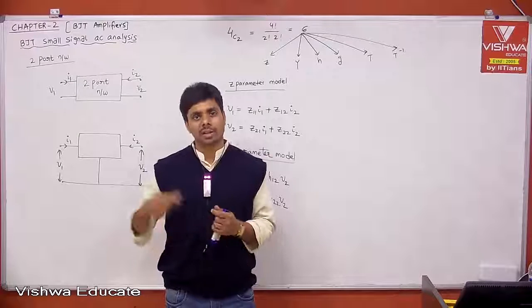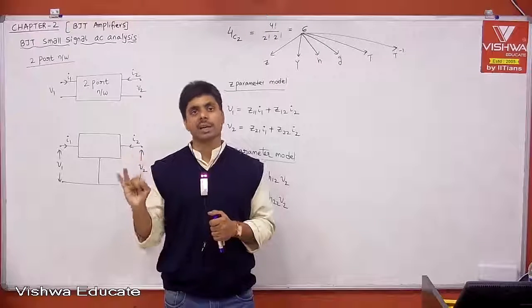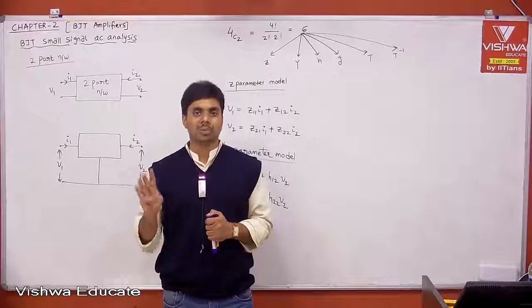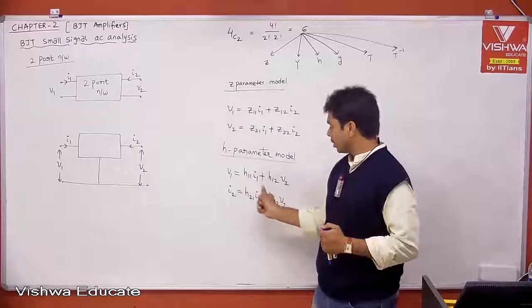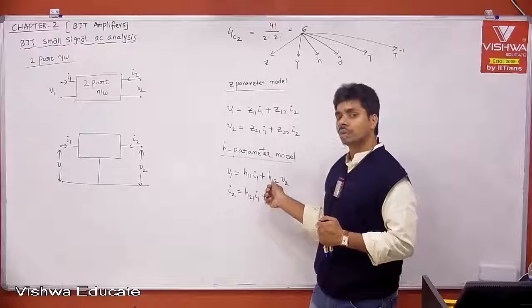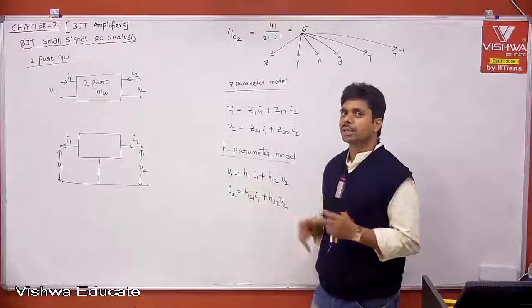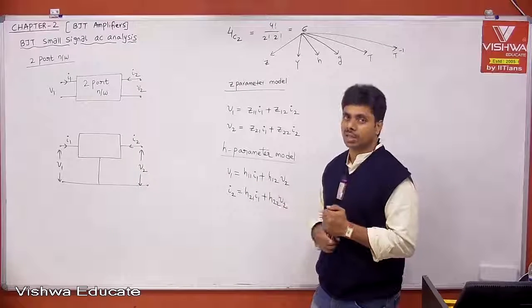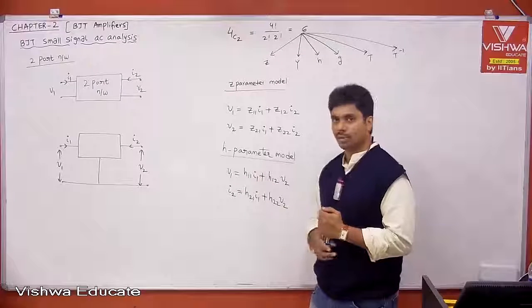For small signal low frequency analysis, they are voltage gain, current gain, input impedance and output impedance. The H parameter model gives input impedance, output impedance, current gain and reverse voltage gain, so indirectly we see the transistor parameters we need for an amplifier. Therefore, it is better to go ahead with the H parameter model.